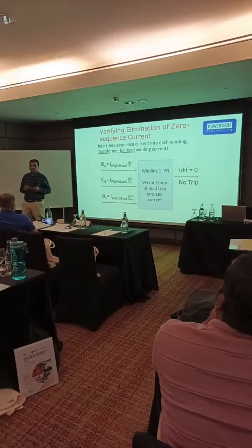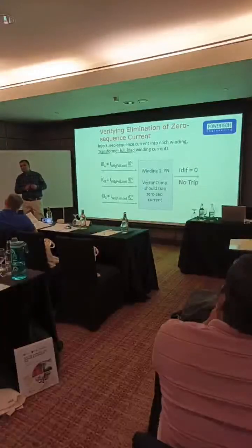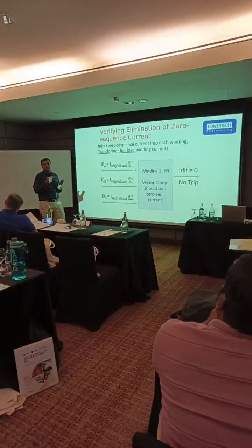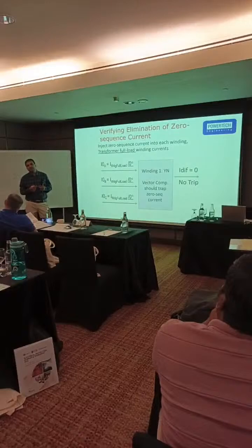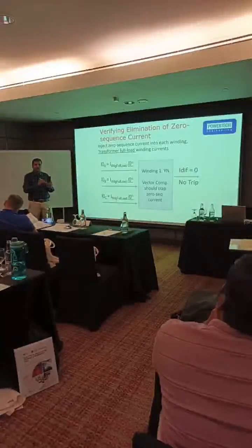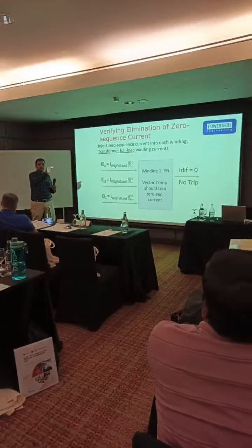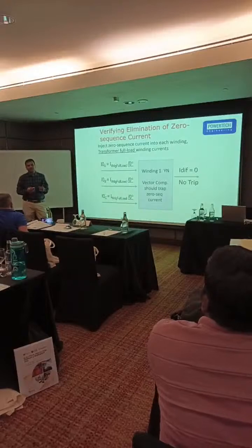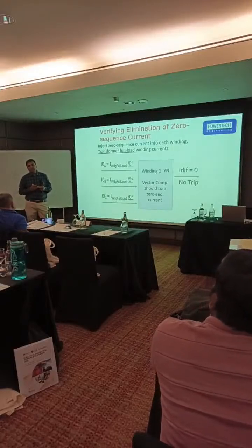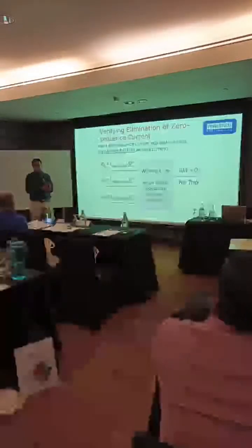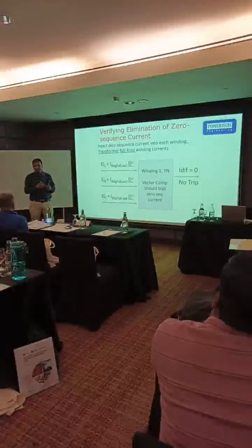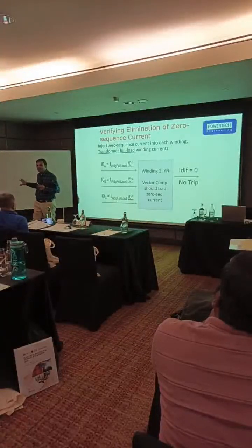So why is this zero sequence current elimination necessary? Actually this zero sequence current is not the differential current. It is coming from the ground, so it is an external current. That is why it creates a problem in the differential relay. That is why we eliminate it.